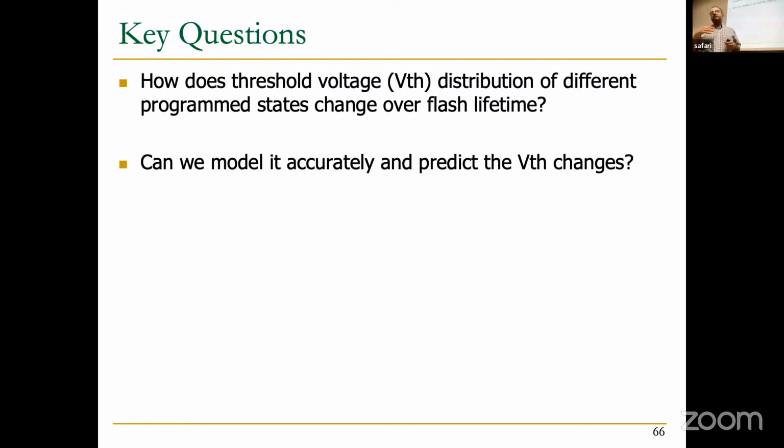And basically, the controller retries the read process. It slightly adjusts the reference voltage and accesses the flash cell again, trying to read the flash with a different reference voltage. This can be very costly in terms of performance and other issues, but performance is one of the main issues. That's one of the reasons, as you will also see in this lecture, that when your SSD is getting aged, its performance decreases a lot.